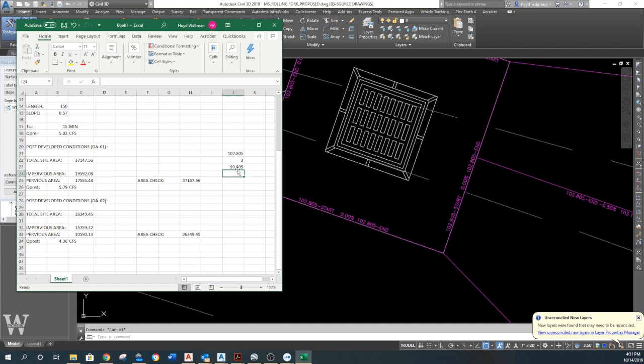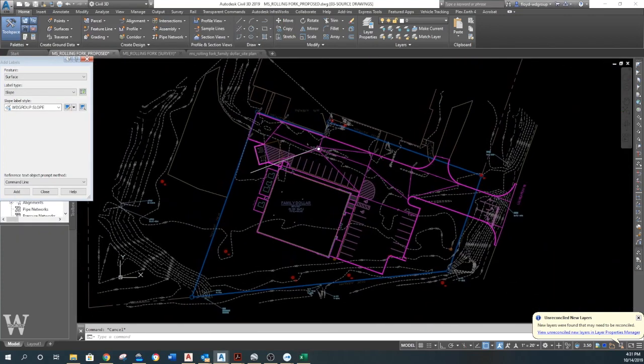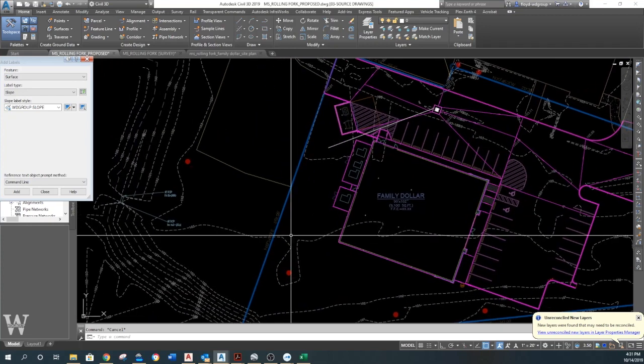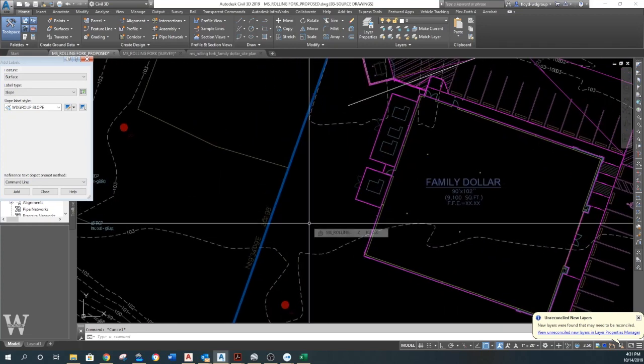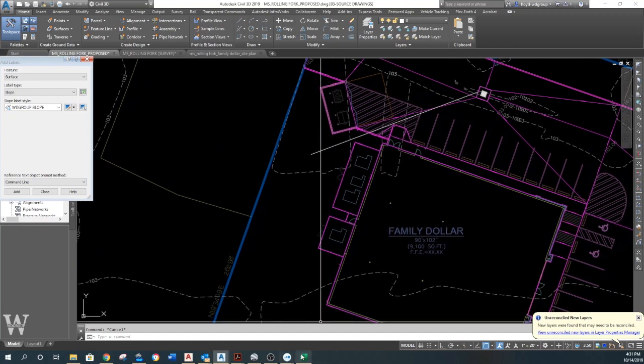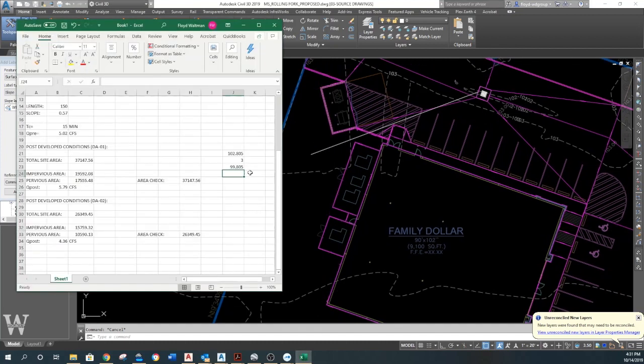Okay, if I didn't quite want 2 foot, if I could get by with a little less than 2 foot of cover, then I could probably set the bottom of the pond at 99. But I mean at 100. That's 3 foot deep. I'm probably going to do that, because that's only 2/10. It's only a couple of inches. Most of my developers are okay. They don't have a little less than 2 foot of cover. We're okay with that piece of pipe coming from here to here. And it'll get deeper anyway quickly as it goes.